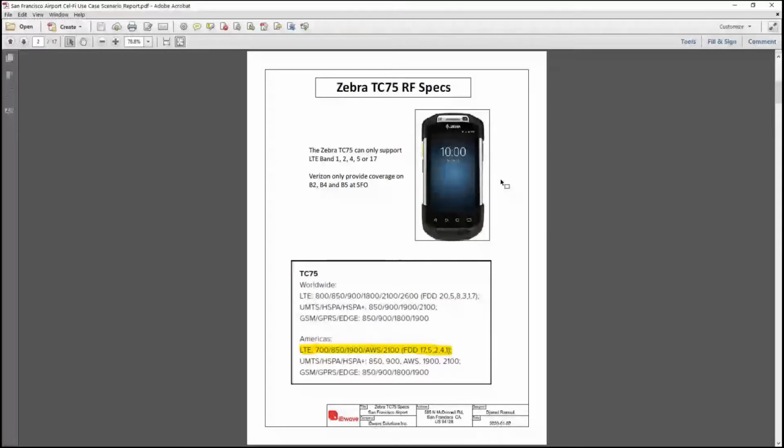With the same sensitivity. If this device has a good antenna gain, then you should get a device with the same antenna gain or the same capabilities. This device supports those bands on LTE, so you want to scan those bands. And once you establish your baseline, you always survey with the same device, so you don't see any fluctuation in terms of difference, because let's face it, a tablet and a phone don't have the same sensitivity, the same antennas, or the same gain.